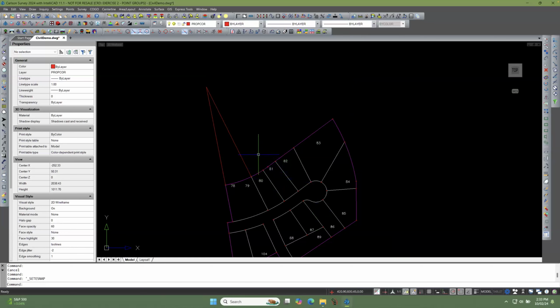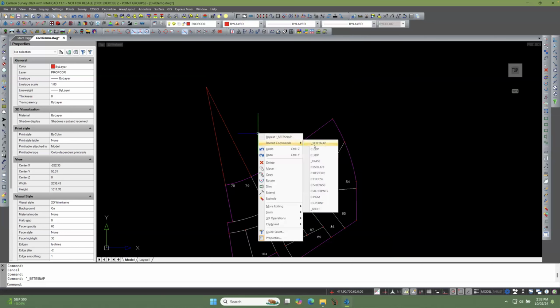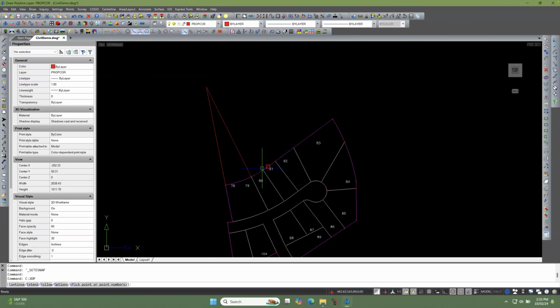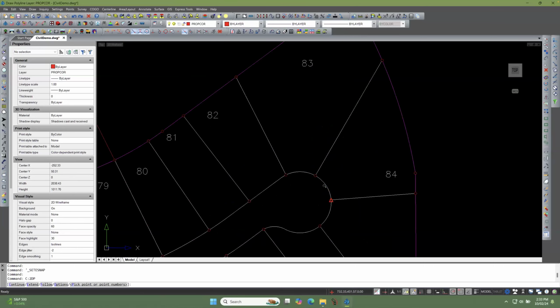Okay, so now if you draw a 2D polyline, anytime you just hover the mouse, you see that is a midpoint. Get closer to the end, you'll get the end point, closer to the middle, the midpoint, closer to the end, you'll pick up the end point, midpoint, end point. Now, these are individual little arcs, so that's an arc from the end point.